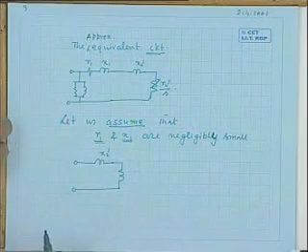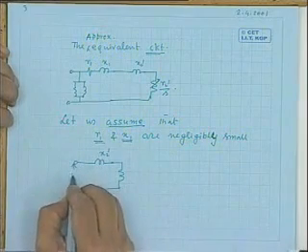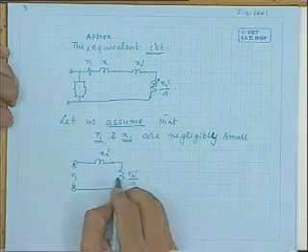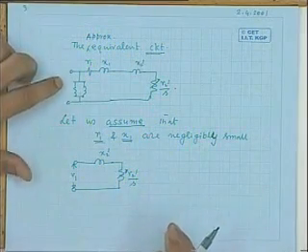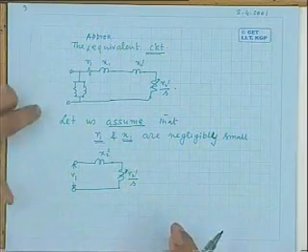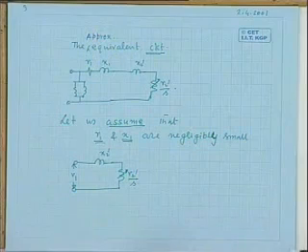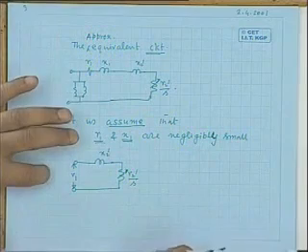That is, on the stator side, there is no loss taking place. So this will be this V1 voltage, and this is your R2 dashed by S when the machine runs at a slip S. So you must understand from this to this what I have done. I have assumed R1, stator resistance, and leakage reactance to be negligibly small. Then the equivalent circuit will look like this.